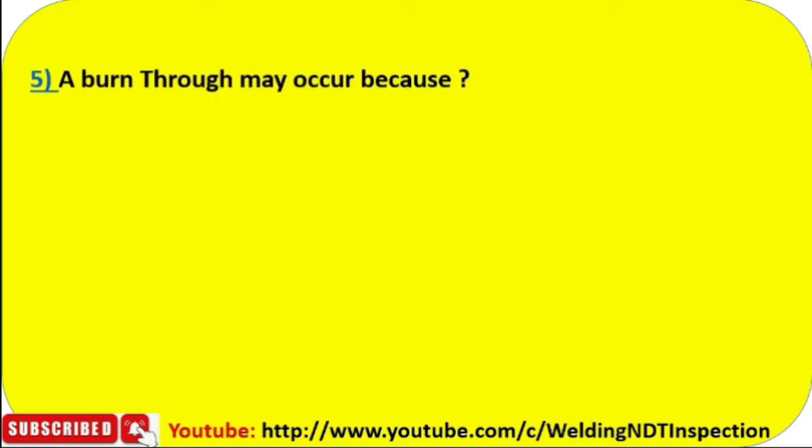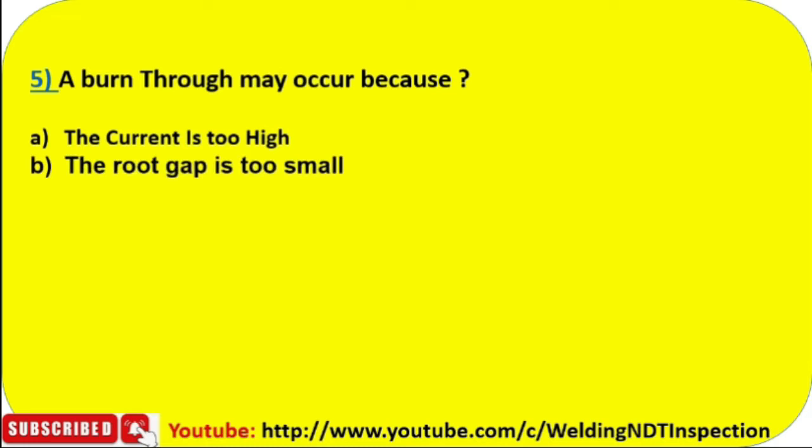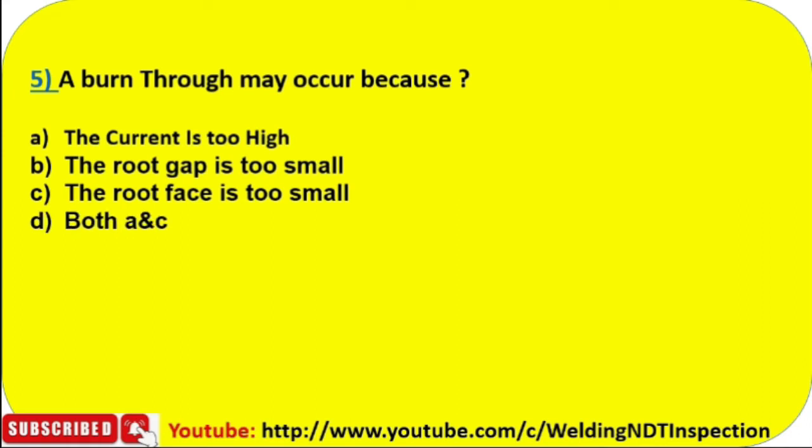Question number 5. A burn through may occur because: why may burn through occur? Burn through क्यों आता है welding में? A: the current is too high. B: the root gap is too small. C: the root face is too small. D: both A and C. So first, the current is too high.